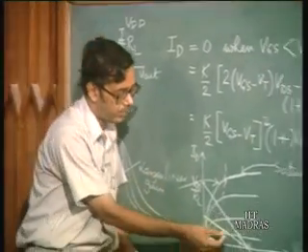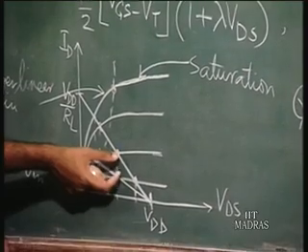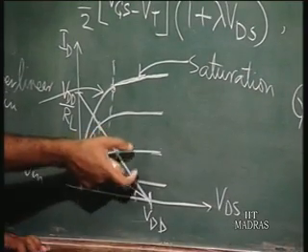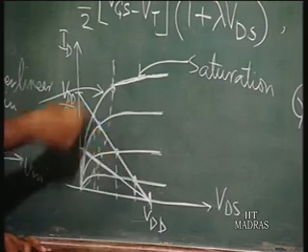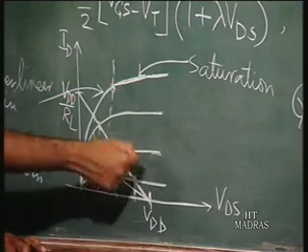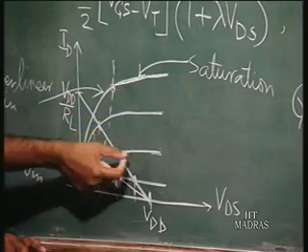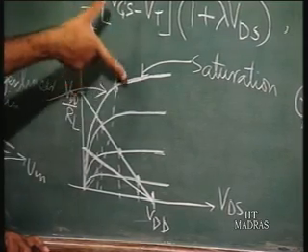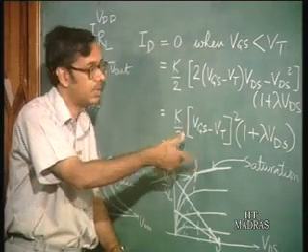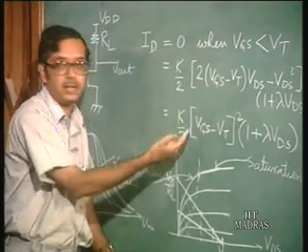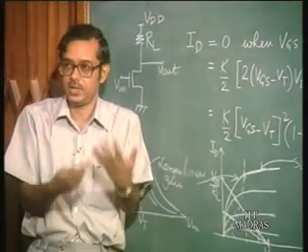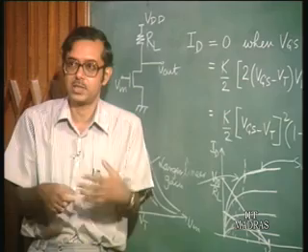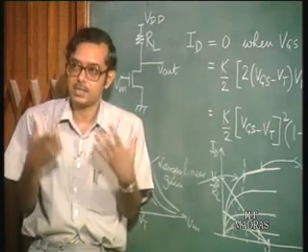It is also quite obvious that if you plot the output characteristics with equal increments of VG, the curves will be more and more separated if you go for higher and higher gate voltages, because the GM increases with VG. At lower gate voltages the GM is less.